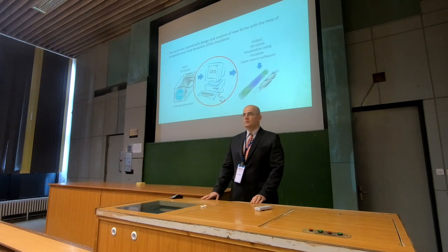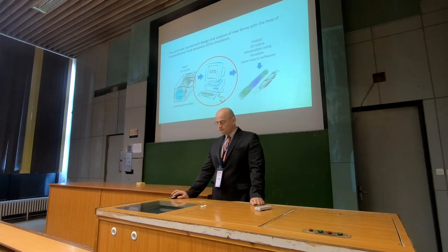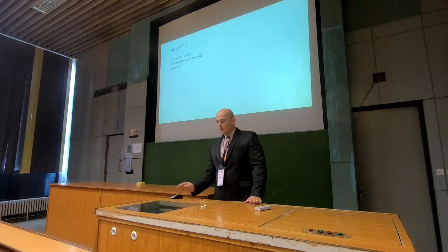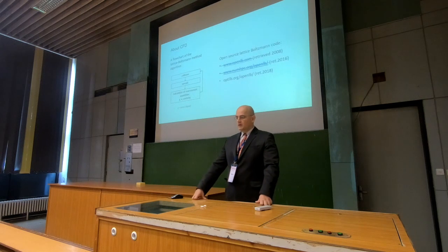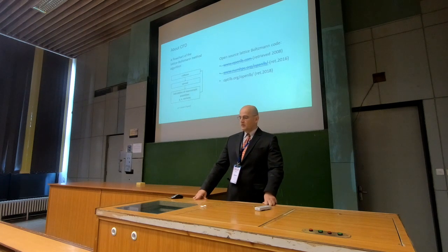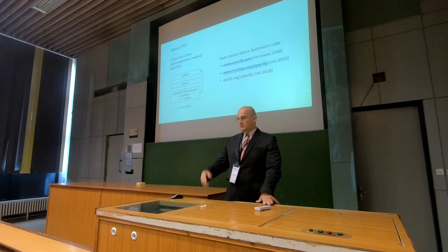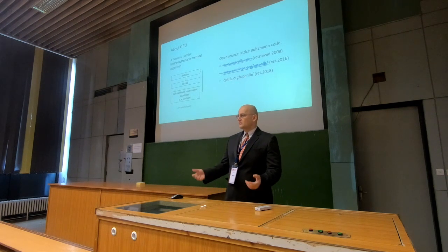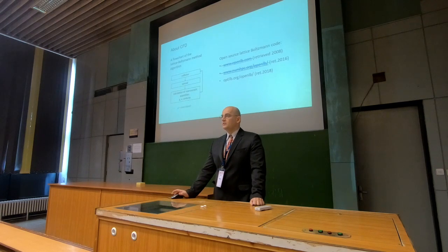Just a few words more about the CFD. We used a lattice Boltzmann algorithm. We calculate for each particle the collision and spread and calculate the macroscopic quantities: the density, velocity and vorticity. Of course, for fluid the density is constant, so we need velocity and vorticity from this.